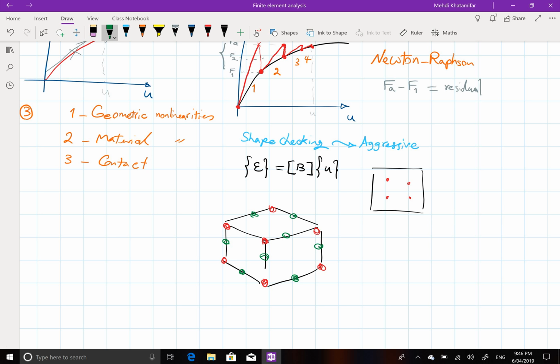So if you are doing nonlinear behavior analysis, we prefer to get rid of these mid-side nodes, because if the element is supposed to stretch and we have a large deflection, these extra nodes are going to create trouble for us, and there is an option for that inside the advanced section of meshing.